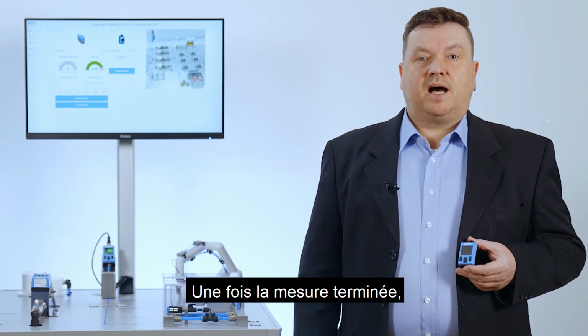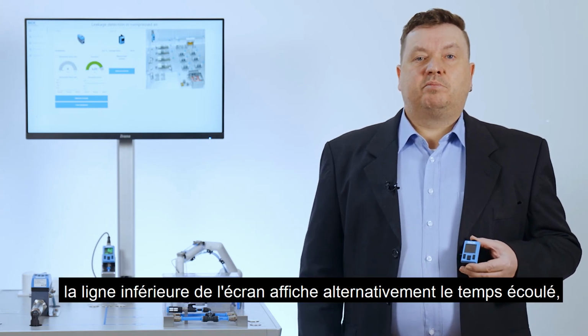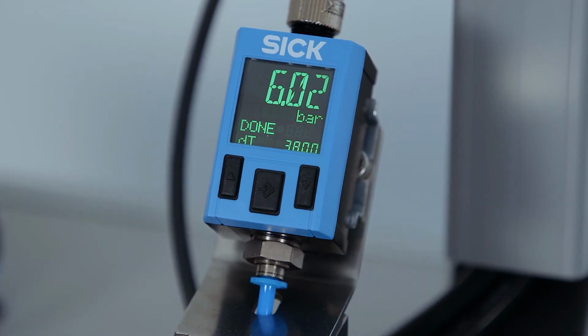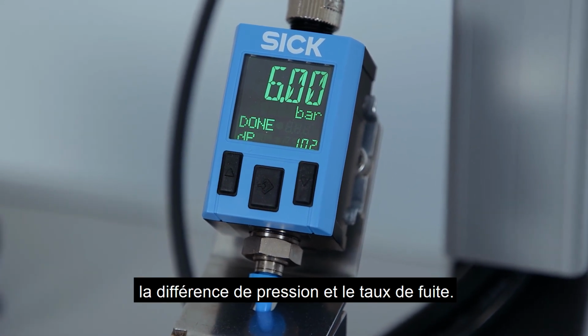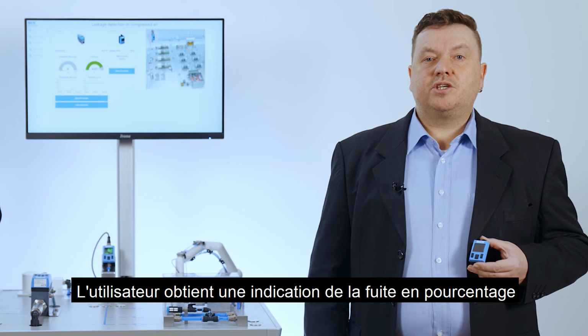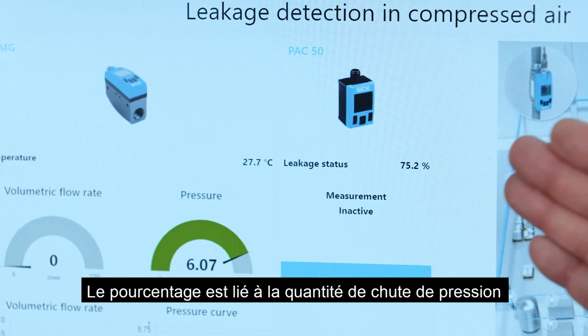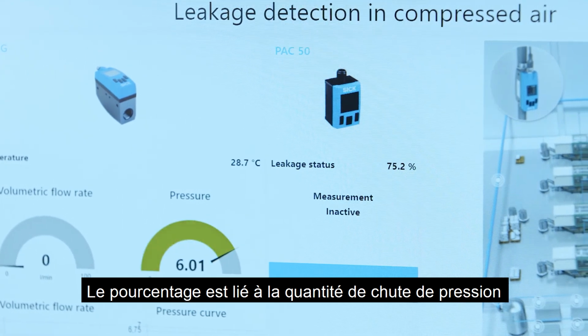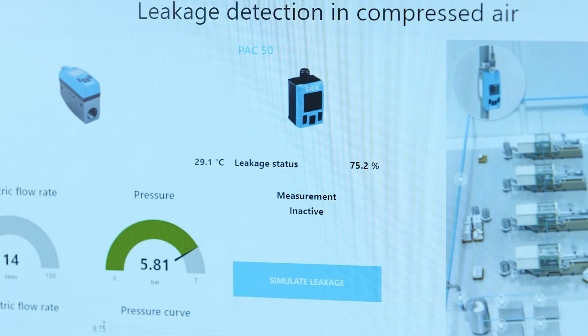After the measurement time has been completed, the bottom line of the display alternately shows the elapsed time, the pressure difference and the leakage rate. In the large display of the exhibit, the user gets an indication of a leakage in percent. The percentage is related to how much of the pressure drop between the two threshold values is already lost.